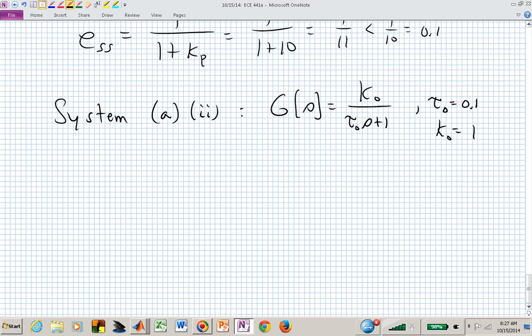It's just a pole somewhere in the left half plane. What would you be keying in on? Now we've derived the steady state error formula for a type 0 system. This has 0 integrators, or 0 poles at the origin. This is a type 0 system.